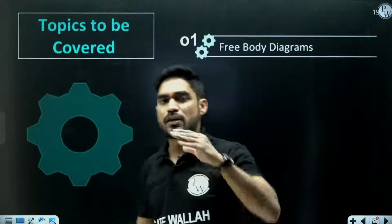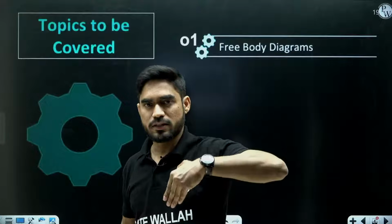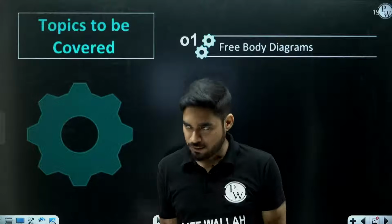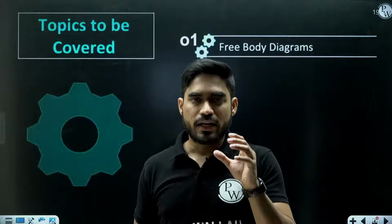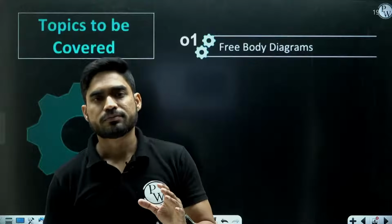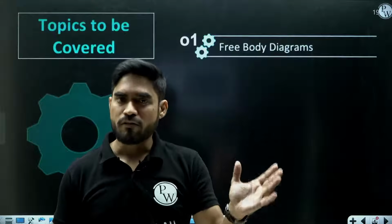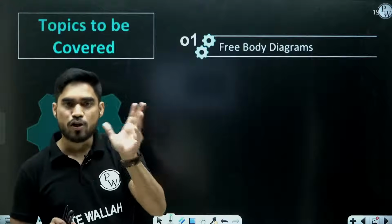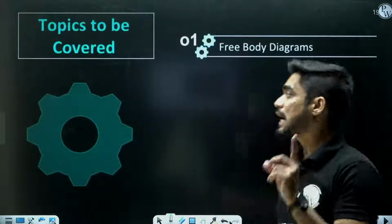So if I isolate the roof from the beam, I will show whatever downward force the roof is applying on the beam. Then when I isolate the columns from the beam, I will show some upward force acting on the beam. So in order to calculate the forces acting on the beam, I need to isolate all the other members and show whatever forces they are applying on this beam. So this sketch of the beam that I will draw will be known as a free body diagram.